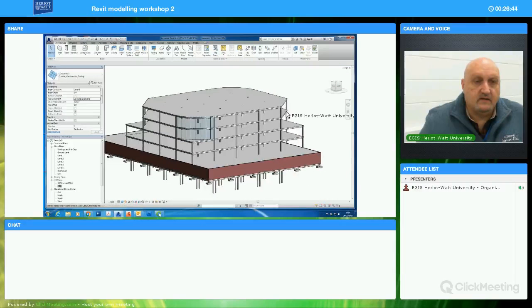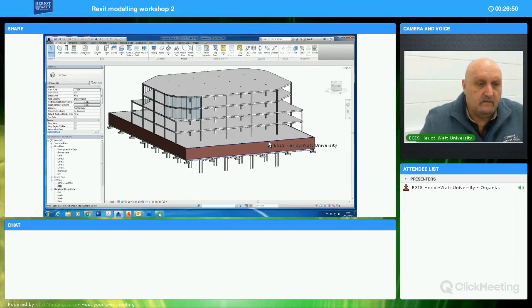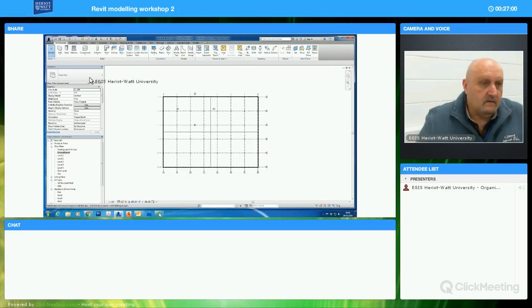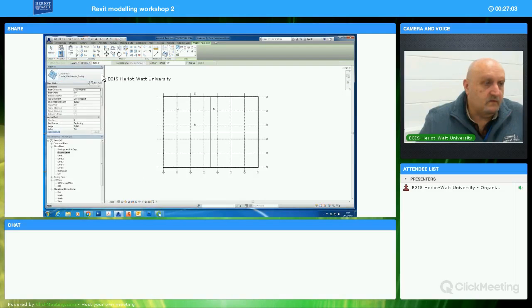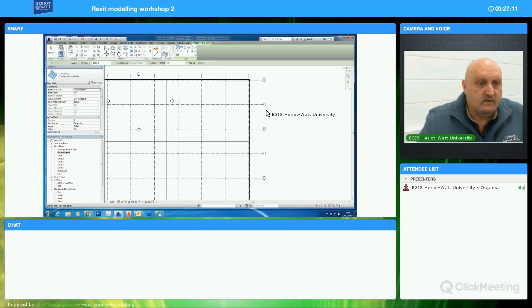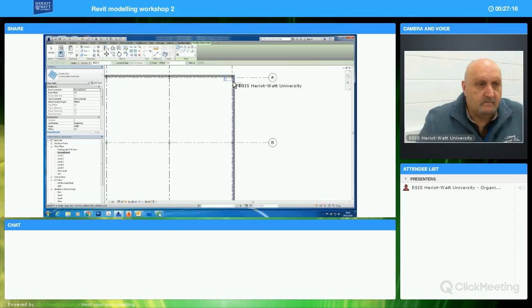So I'm not going to bother doing these other two. Clearly you can see how that works. But I will show you how to put in the storefront walls into these brick walls on the ground floor. So I'm going to go to the ground floor plan, and I'm just going to put in some curtain walls embedded within the brick walls. I use this option here, the curtain wall storefront, and I'm just going to kind of randomly set some walls in here. I'll come in quite closely and I'll make some of them small, and you'll get this odd